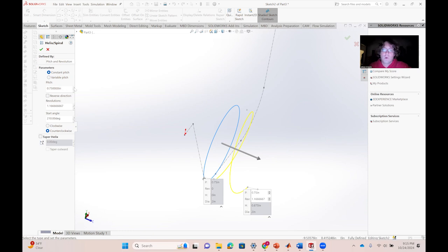I could make this more or less, depending on if I had a different ball, or if I just wanted to make the track a little bit wider. A couple of things are at play here. If you have a very wide track for the ball that goes in it, it might move around to the sides. Generally, there'll be less friction, because on a very flat surface, a ball has a very small contact patch. But as a ball is rolling and meeting a curvature, there's a lot more friction at play there. So if you wanted to make your channel a little bit wider to accommodate that, and perhaps reduce friction, that could be a strategy.